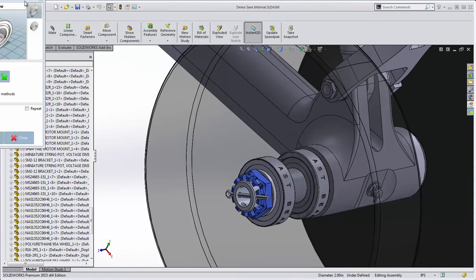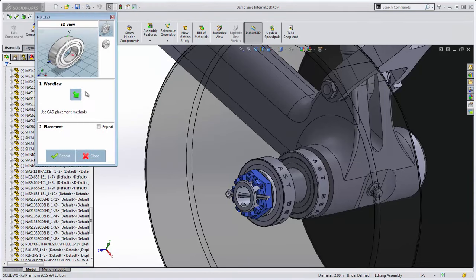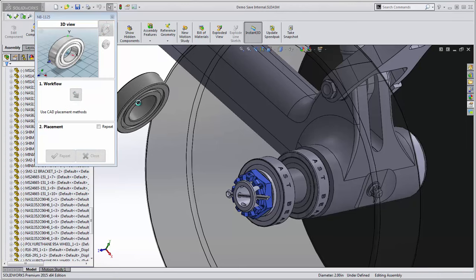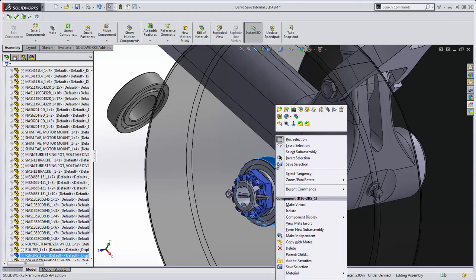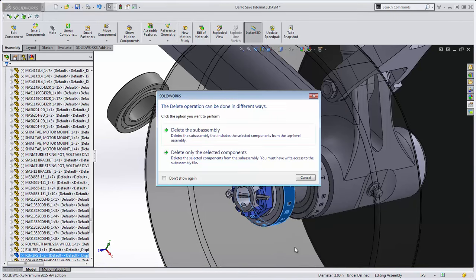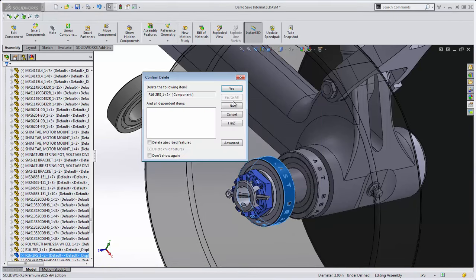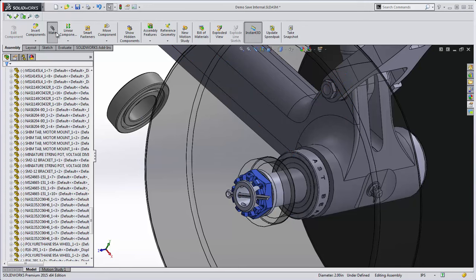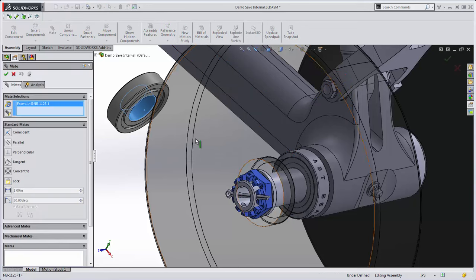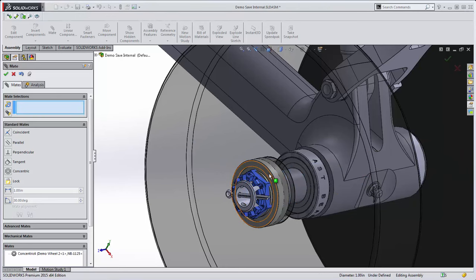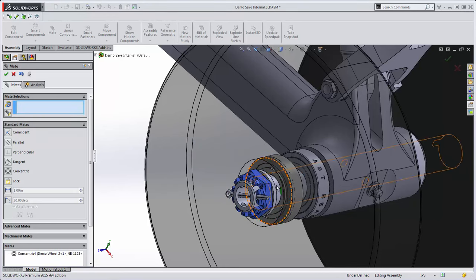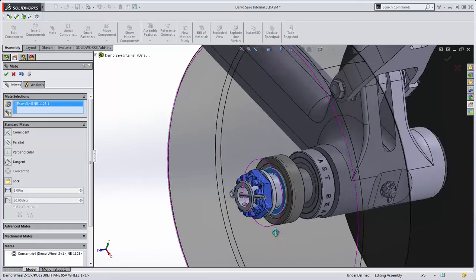Once generated, we can place the part and replace the old component. This feature highlights how easy it can be to use the geometric search capabilities to replace parts in assemblies, in addition to showing what is possible with the PARTsolutions configurations and how PARTsolutions can be used to help drive designers to use preferred parts from preferred suppliers.